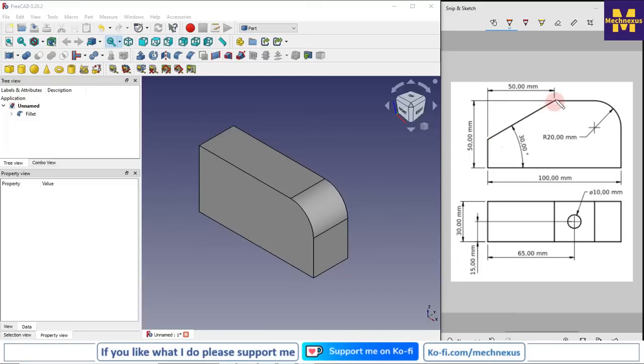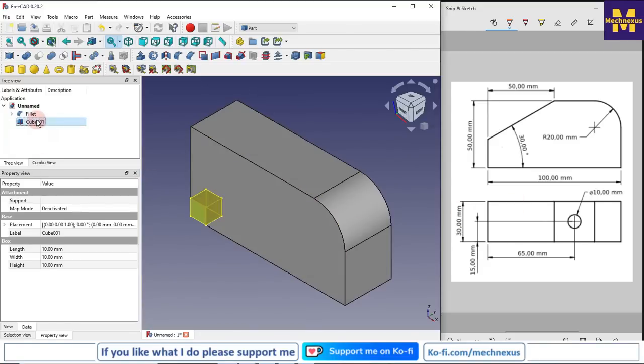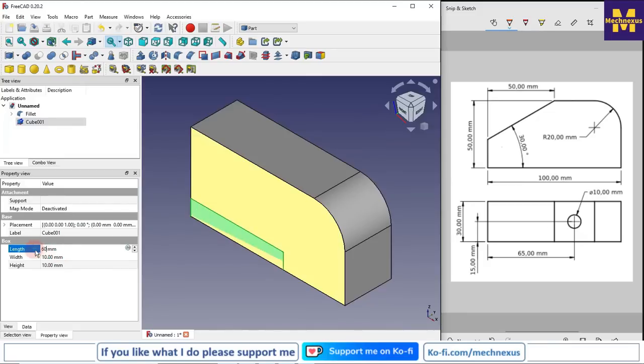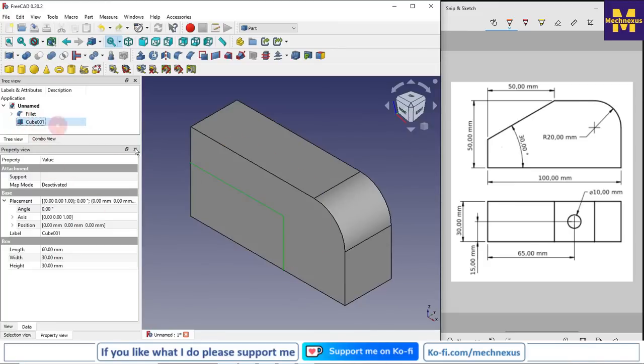Now we will remove the material at this portion. So we will again insert a cube, so it got inserted here, and now we will select our cube and we will give our dimensions. So its dimensions I will give length 60, width 30 and height is also 30. Now we have inserted the cube.